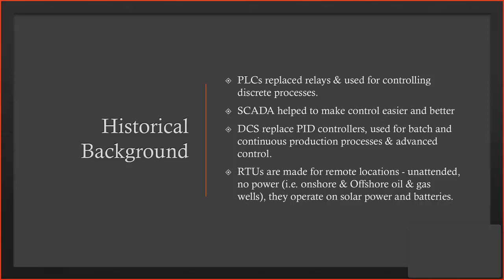So what was the issue? The issue was the communication between those two PLCs. There were some problems. Those PLCs were not able to communicate; the communication was not open. Even if you implemented the SCADA, sometimes the SCADA could get the data from the Siemens but not from the Allen Bradley. I am just giving you an example. Sometimes the SCADA would get data from the Allen Bradley but not from the Siemens. That was a major issue.